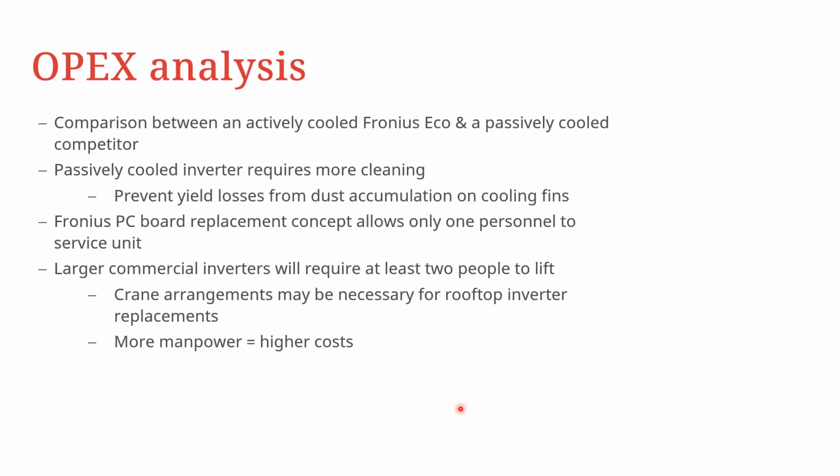So in terms of the OPEX analysis, we have here also a comparison between an actively cooled Fronius Inverter Eco and a passively cooled competitor inverter. With a passively cooled inverter, you would normally require more cleaning to make sure that you do not get yield losses from accumulation of dust on the cooling fins, because with the accumulation of dust, the inverter is not able to cool itself sufficiently and therefore automatically derates the power output.